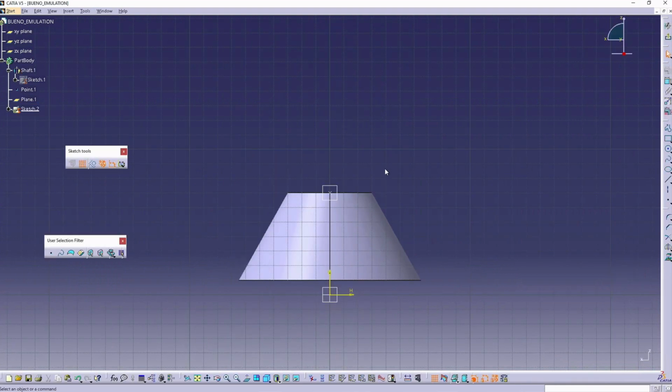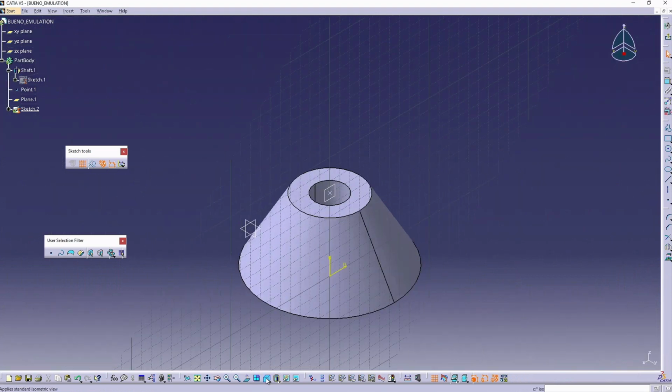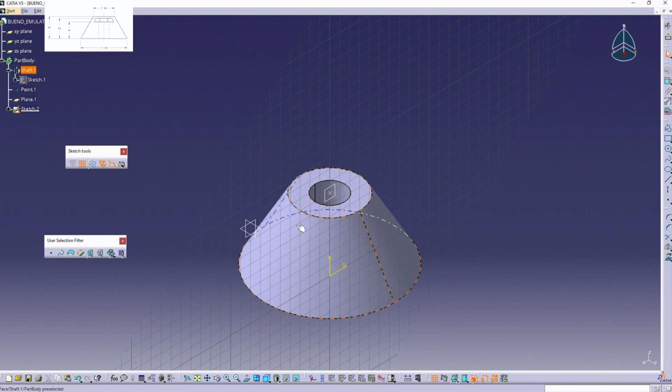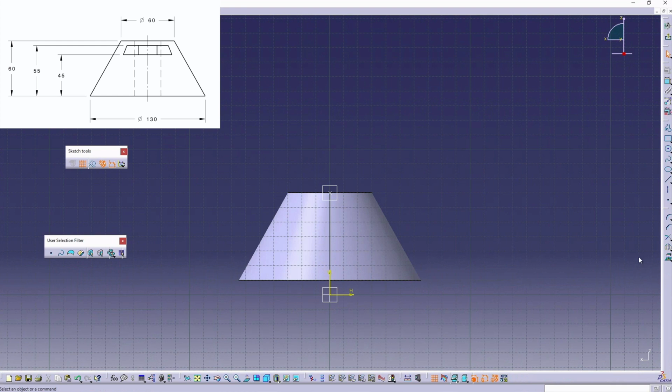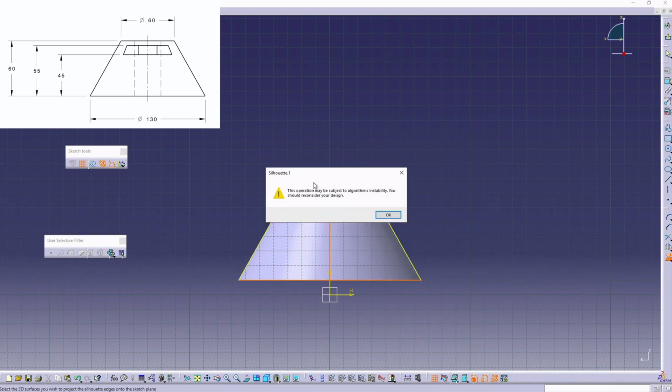Now on Sketcher under plane, we can trace the solid object onto my new sketch. We can check the location of the edge we want to deal with using the isometric view button, and putting it back using the normal view button, we can use the project 3D canonical silhouette edges to trace the projection of the cylinder onto my sketch.